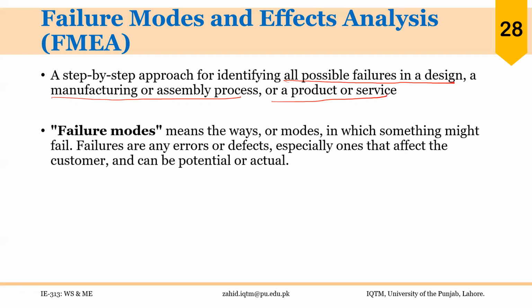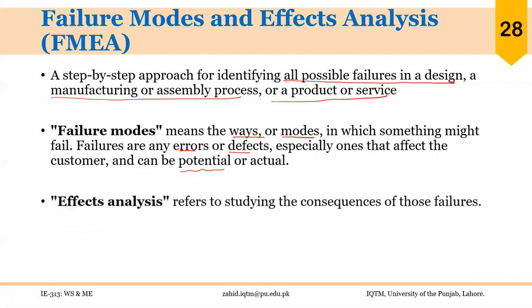Now, there are two sets of words in this name of the tool: failure modes, and effects analysis. Failure modes means the ways or modes in which something might fail. Failures are any errors or defects, especially ones that affect the customer and can be potential or actual. So you can actually look for potential problems beforehand and make sure that they do not occur, or they could be actual problems as well. Effects analysis refers to studying the consequences of those failures.